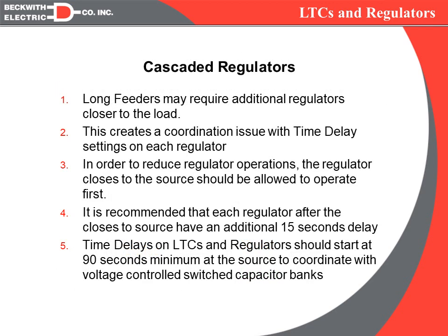So, in summary for regulators and LTCs, we are going to possibly need additional regulators outside the fence for long circuits. When we do that, then we have to coordinate the regulators back with the upstream. And the general rule of thumb is you want the regulation closest to the source to have the shortest time delays. And then you want to extend the time delays as you go down line by about 15 seconds. And typically we want the time delays inside the fence to be starting at about 90 seconds because we want to allow the capacitor banks time to operate first.